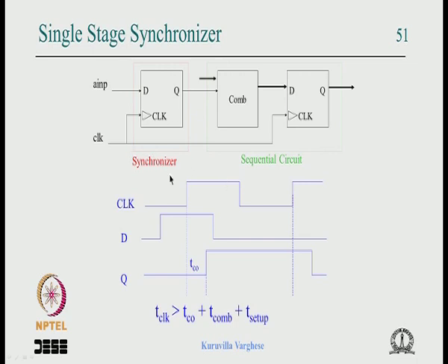Now as I said, we have not solved the problem in a very foolproof way. Earlier there were chances of all these or some of these flip flops getting into metastability. Now there is no guarantee that this will meet the setup and hold time of this flip flop, because this is asynchronous with respect to this clock. So this can get into metastability.